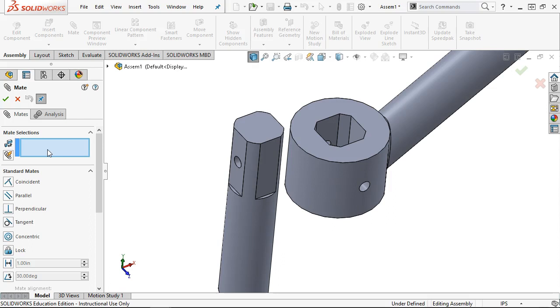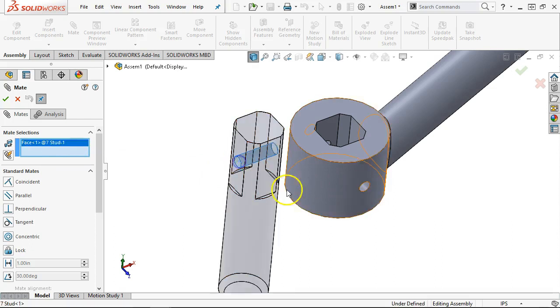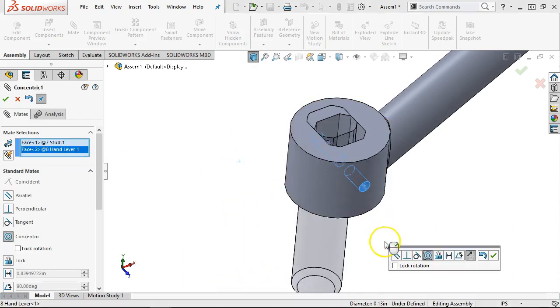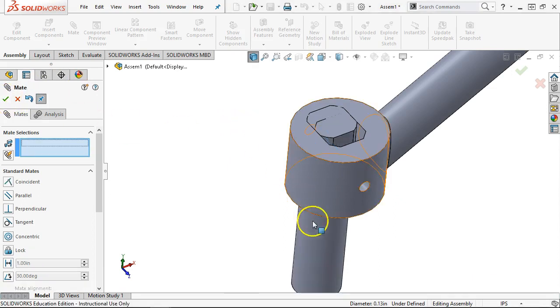My workflow is I'm big on pre-select, big on the control button. So a lot of times when I slip into my assembly mode, it is all going to be pre-select. And then once I'm in the property manager, we'll go ahead and pick. All right, so cylinder to cylinder in this case, and then it rotates into position. And we'll go ahead and accept either from the pop-up or from the property manager. Go ahead and hit OK.